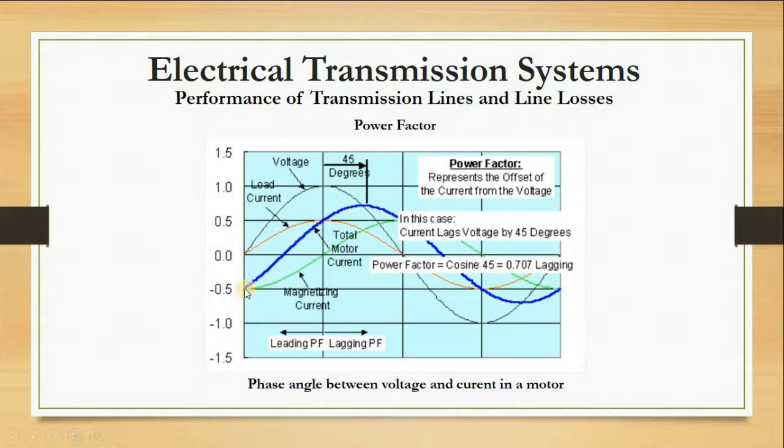But then when you look at the magnetizing current, because that goes into the coil and you know the behavior of the coil, we expect that the voltage should lead that current which is going through the coil, the magnetizing circuit. So let's see whether truly the voltage is leading this green waveform which represents the magnetizing current.